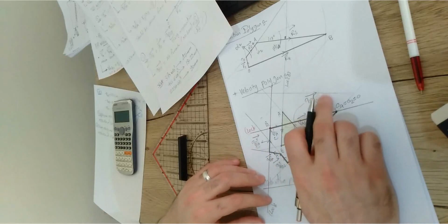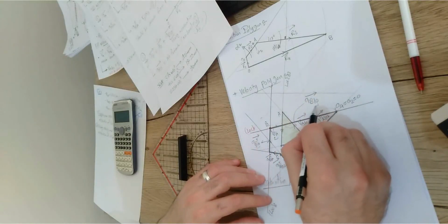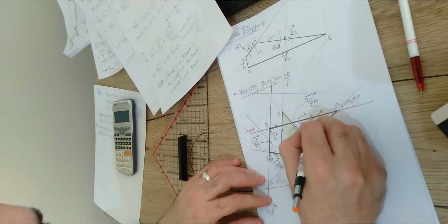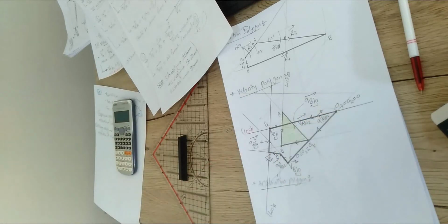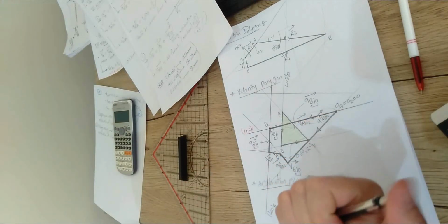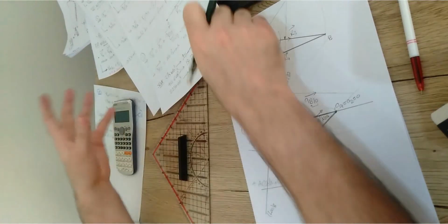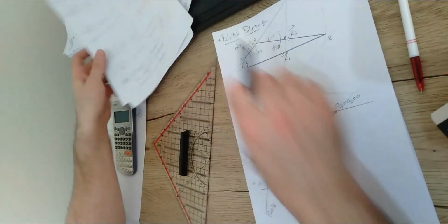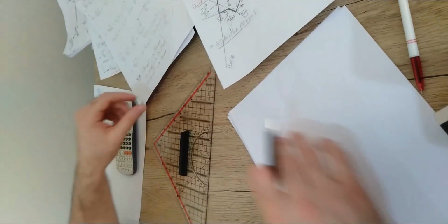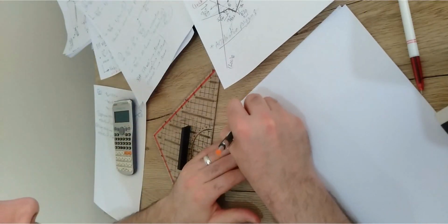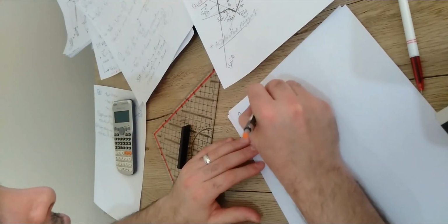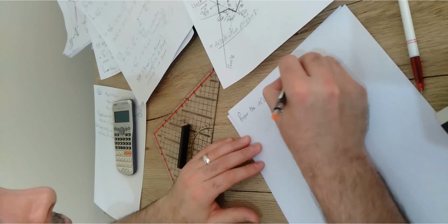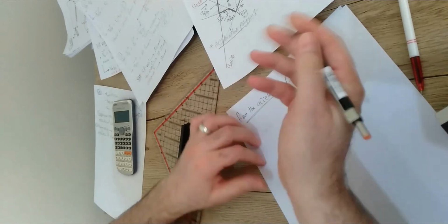How about the AB relative to O? It should be moving from O to B. From O going to B, so this should be the direction. The direction of this one should be going from O to B. Make sense? Then what you're gonna do, we're almost done. Your objective is just to find the unknowns. So using another drawing sheet for the acceleration polygon, you're just gonna measure the unknowns.